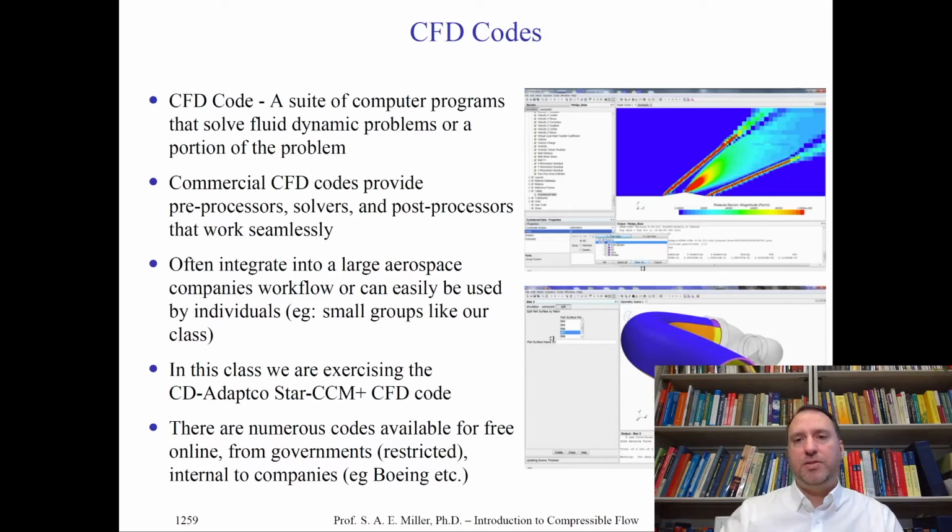In the upper right, you see one of the famous problems we solved in this class. There's a wall, and the blue part is a fluid, moving supersonically from left to right, and you see one particular shock wave, an expansion, and another shock wave. So this is a shock expansion problem which we can solve with CFD. Thankfully, this problem also has an analytical solution, and so we can compare our CFD result with the analytical solution to see if it's correct.